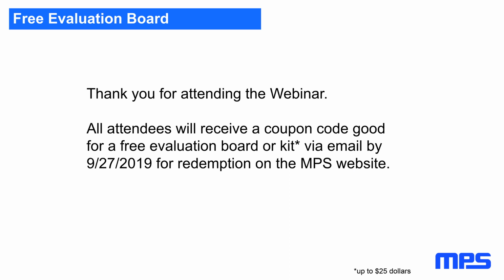You can actually make yourself a shielded inductor by placing a conductive material not directly onto the magnetic material, but with a space of, say, 1 millimeter. This additional air gap between your shield and the inductor typically makes the losses go away. So you have very little additional losses from your shield if you have an air gap between the inductive material, the ferrite or the molded iron powder, and the shield.